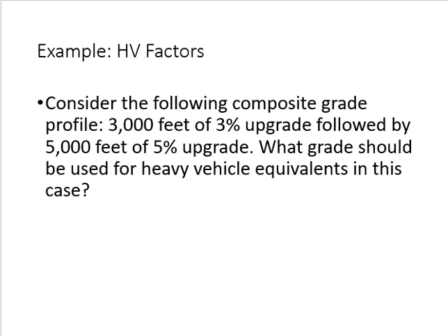Multi-lane highways and freeways have very long segments. So it's very uncommon that you have a long segment with one gradient. The gradient may change. In that case, we need to combine the gradients into an average value. To calculate the average gradient, we use the total height and total distance. Gradient is height upon distance, right? So we need the total height and total distance.